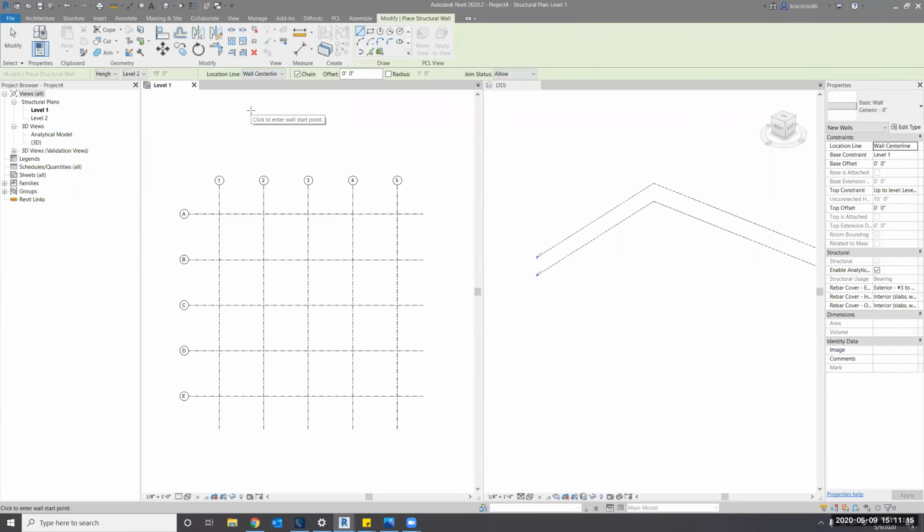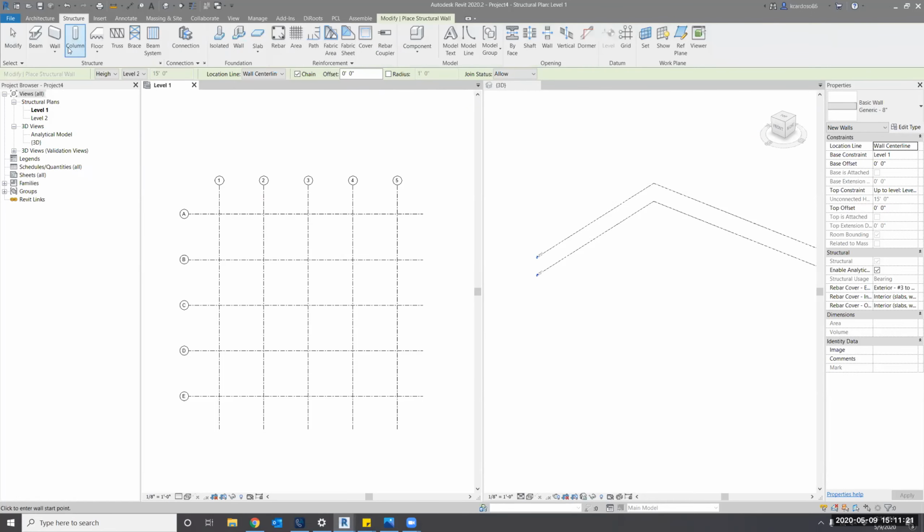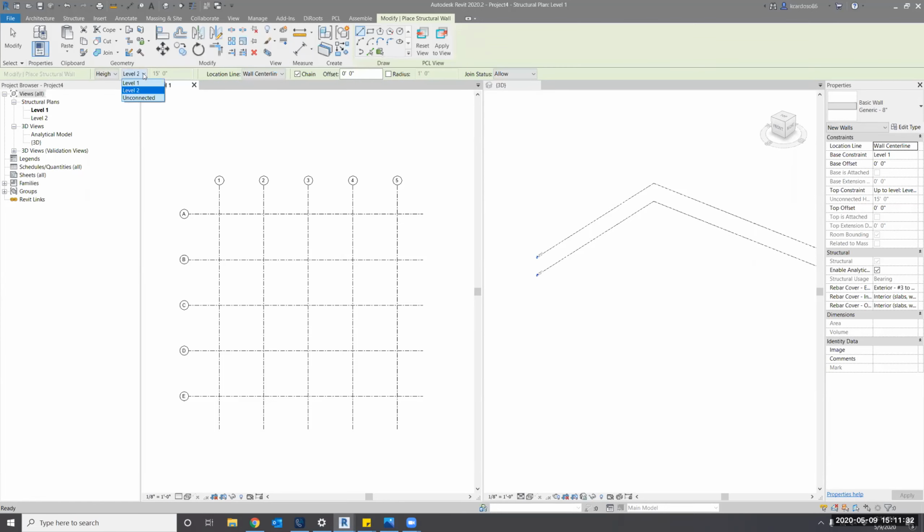If you're using your mouse, I like the workflow that the mouse has to go through. So if I go Structure, Wall, the next automatic place that the mouse goes to is this options bar. So I'm at Level 1, height. I want to go up to Level 2, and I want to do Finish Face Exterior.